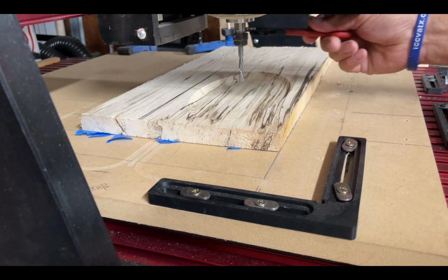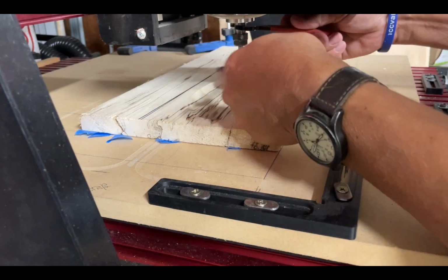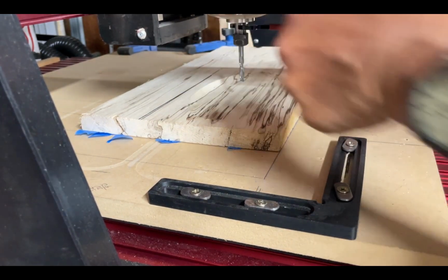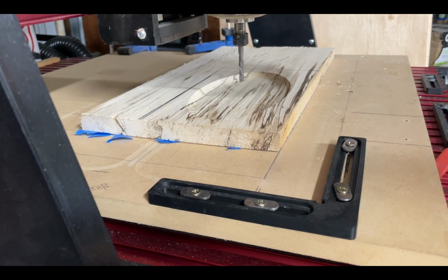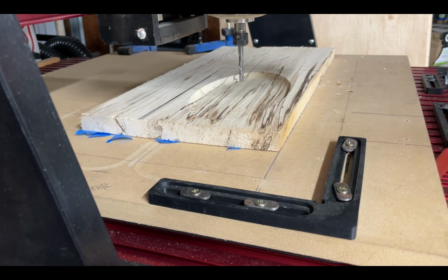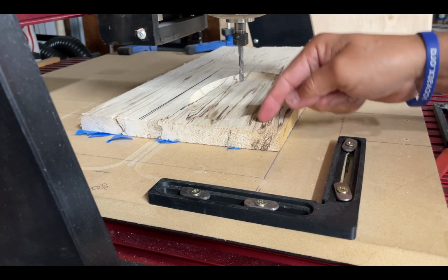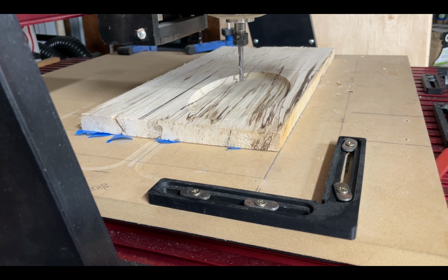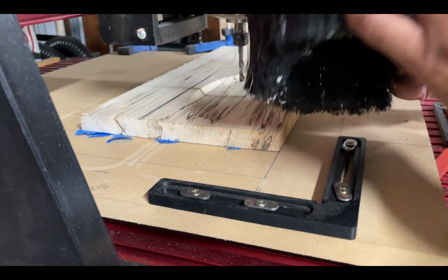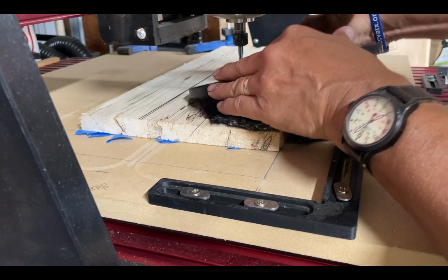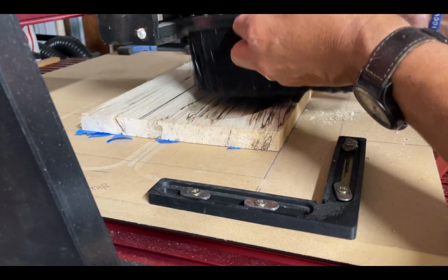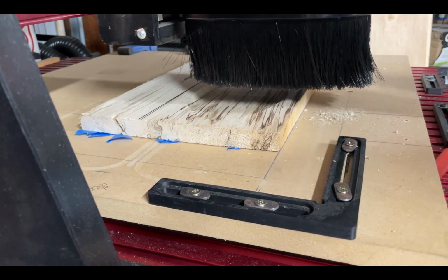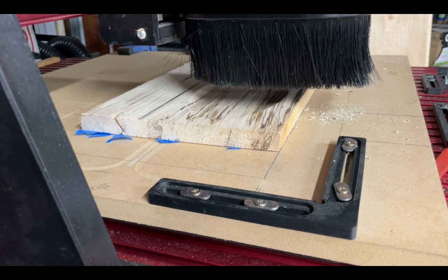We are going to go ahead and put our dust boot back on. I'm just going to double check that I've gotten this bit tightened enough. Yeah, that's pretty good. I'm going to put our dust boot back on because this will make a little bit of a mess, but we'll see this end mill move to the edge, and then go around probably about 6 times because I like to take off just a little bit of material at a time. Perfect. And let's go ahead and run our software.